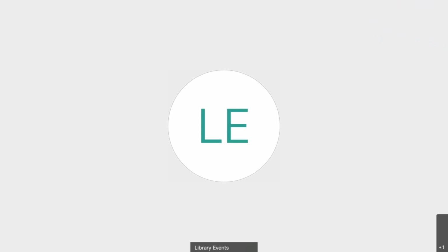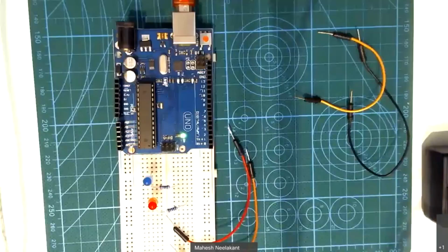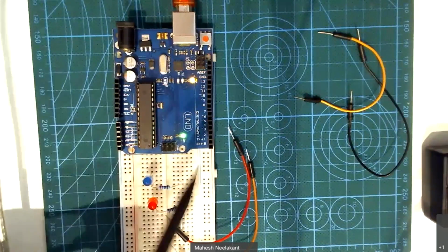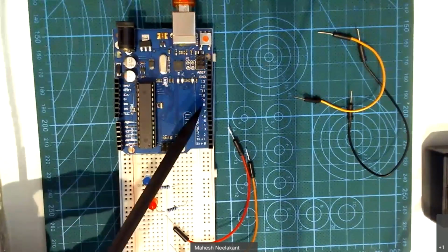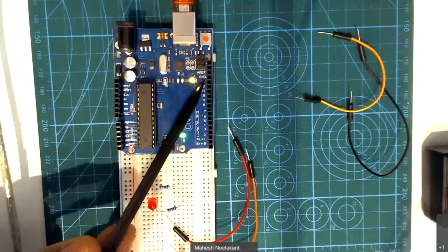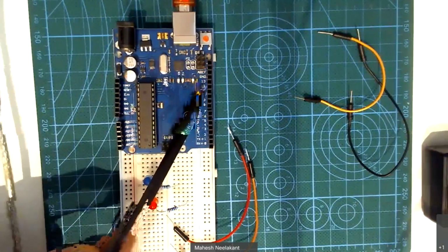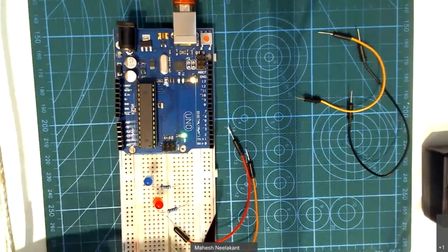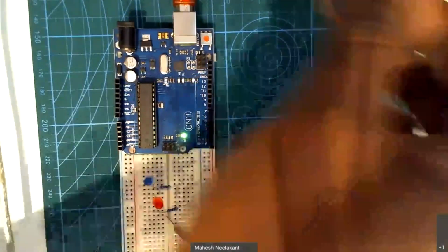Yes. Okay, cool. All right, so let's finish building this circuit. If you go to the website, you'll actually see the circuit. I happen to have it on my other screen. So the first thing they tell you to do is basically wire up pin 13, which is right here, to the breadboard. And it doesn't matter where in the breadboard it is. So I'm going to go ahead and connect up my pin 13.